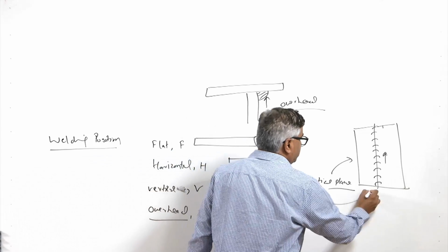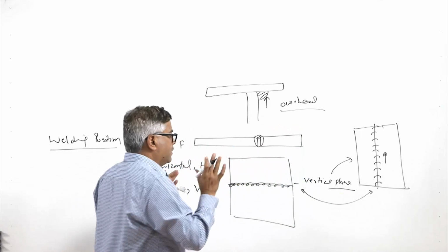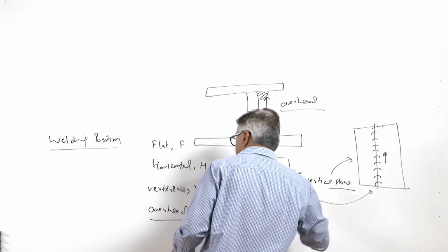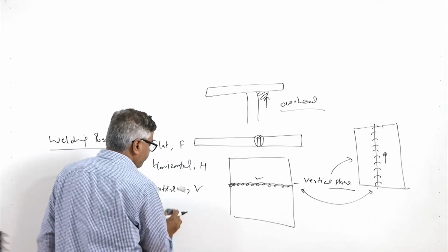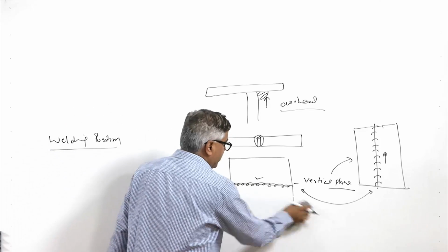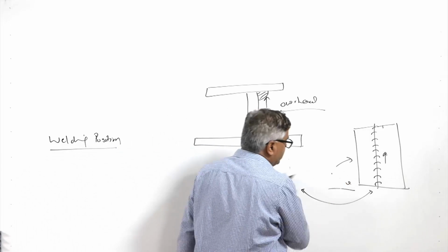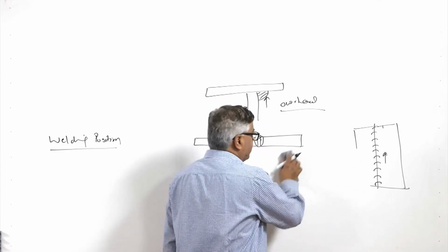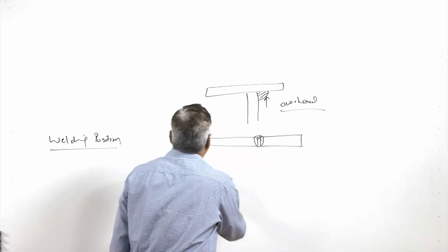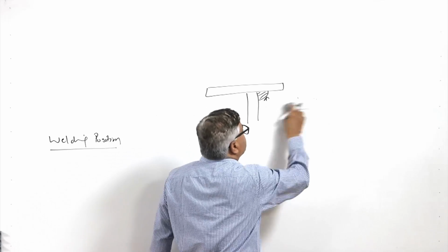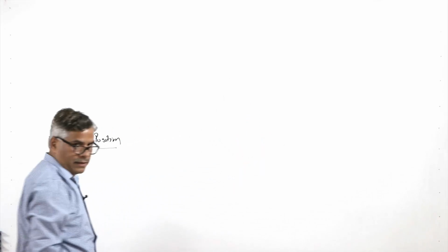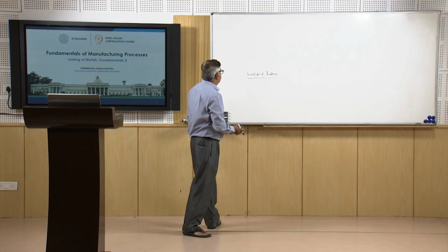Similarly, control of the heat input as well as proper control of the molten weld pool is also needed in horizontal and vertical welding, because the molten metal will be placed in a vertical plane, which will have a tendency to fall down. The maximum tendency to fall down is observed in overhead welding, thereafter in vertical welding and horizontal welding. So, very close control over the heat input and molten metal, and the skill of the operator, are factors that play an important role in successful welding in vertical, horizontal and overhead positions.